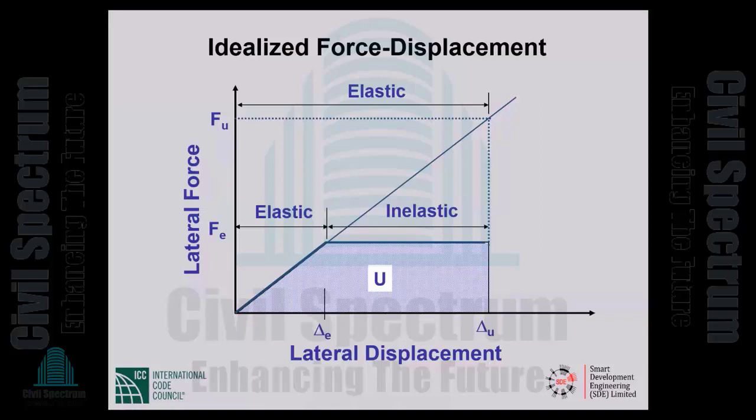As the earthquake induced forces equal and then exceed F sub E, the structure will start cracking and yielding in places. That will be the end of elastic displacements and the beginning of inelastic displacements, which will not follow a flat top as in my idealized picture, but anyway, the point is that now there is damage associated with the displacements. The earthquake passes, we will not get our structure back intact. The damage will have to be repaired.